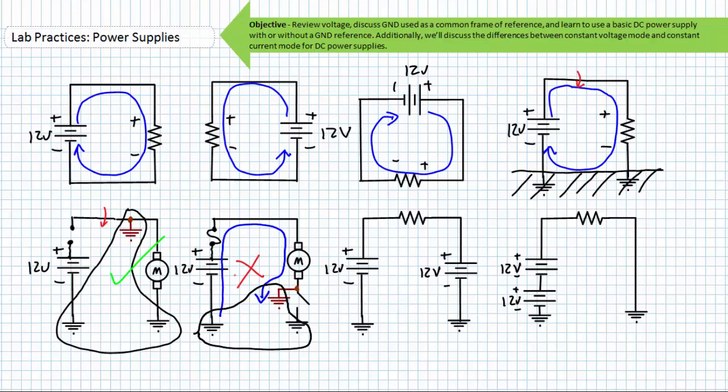Okay, moving on. Our next example shows two opposing voltage supplies, both referenced from ground using the negative terminal. Visually, one could think in this manner. Start at ground, go up 12 volts. Start at ground, go up 12 volts. What is the differential between the two terminals of this resistor? If it's 12 volts on one side and 12 volts on the other, there is no differential between the two terminals and current will not flow.